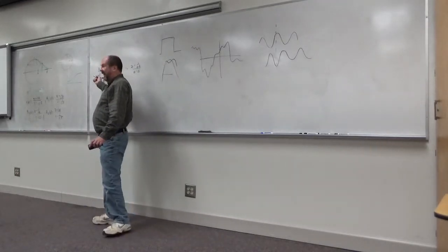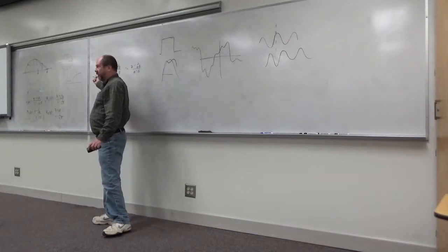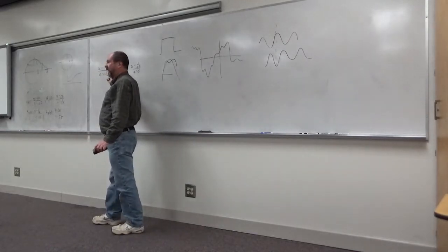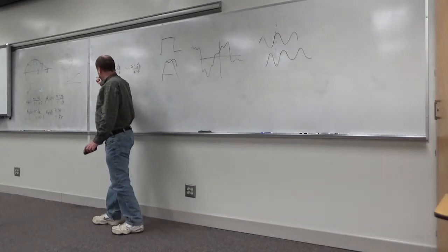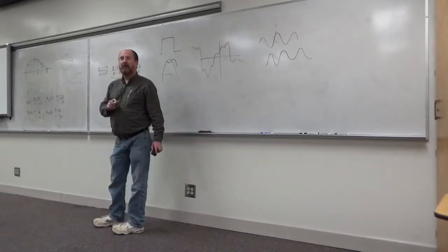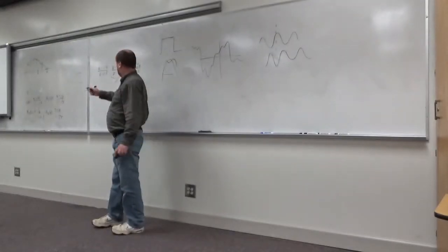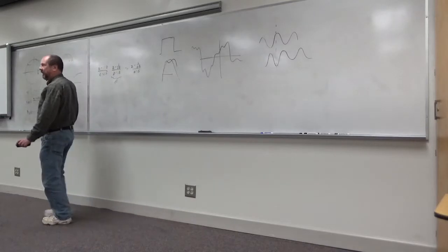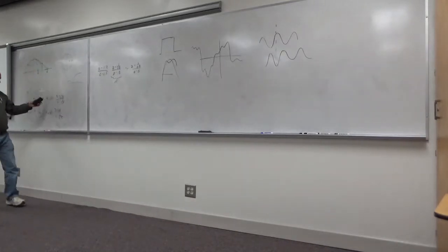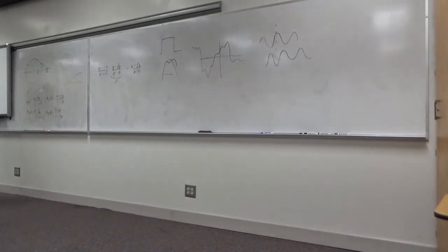So if I multiply a particular filter here by an all-pass filter, the all-pass doesn't affect the gain. So the gain response of that one and the gain response of that one will be the same. Okay? And to get those others, how would I do that? Just multiply by different all-pass filters. Okay? They will all have the same gain response.